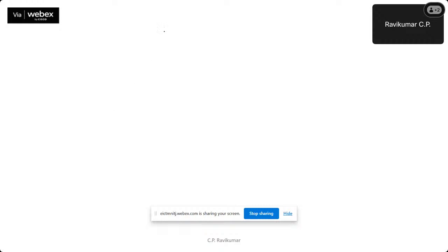Memories in the beginning, and we talked about volatile and non-volatile memories. During the class, I believe we talked mostly about testing of RAMs, especially SRAMs and DRAMs, right? And in particular, we talked a lot about the marching tests. These involve writing patterns into memory and reading them back.